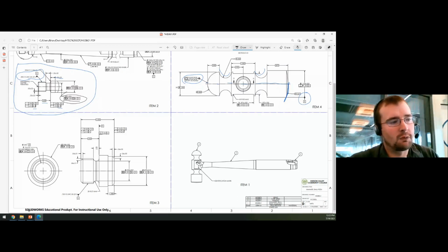The other thing is profile of a surface is used for more than it was traditionally used for. I'm curious to see what your feedback is on this, even if you email me after this. Profile of a surface is used way more than I've really seen it in the past, within the last 5 years. I'm not sure if it's a new engineering trend or they're really fully starting to understand it more, but we do a lot of profile of a surface: how to inspect it with the coordinate measuring machine, which makes things nice, how to do some work with the comparators if you have to, and how to do it on the plate when you can.